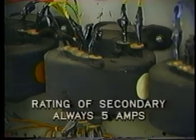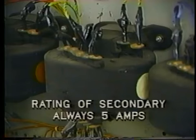Note that in all cases, the rating of the secondary is 5 amps. For the relay, the most important aspect of the CT is its accuracy in reflecting the current at fault levels, which may be at least 10 times normal load current.